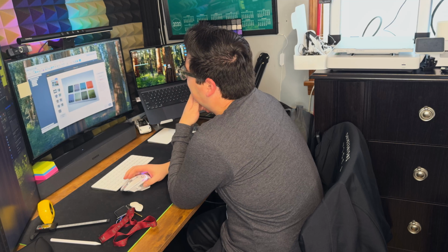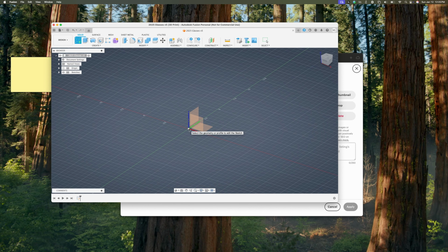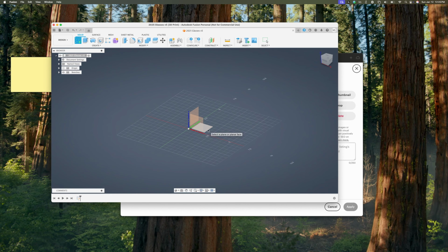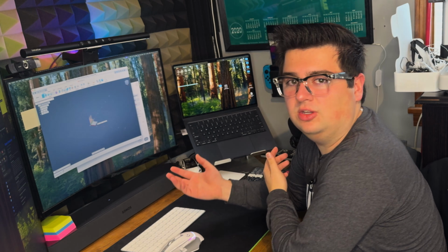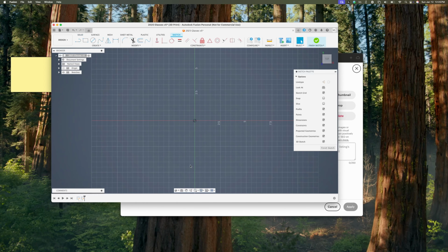So I'm just going to build my own, and I think it would be a great way to segue into building a tutorial. So first you've got to make a sketch, and you click this little create sketch button up here, and then you decide what plane you want to take it on. And pretty much always, when you're building something from scratch, you want to start on this plane here. On basically the ground is the best way to put it. So we'll click on this.